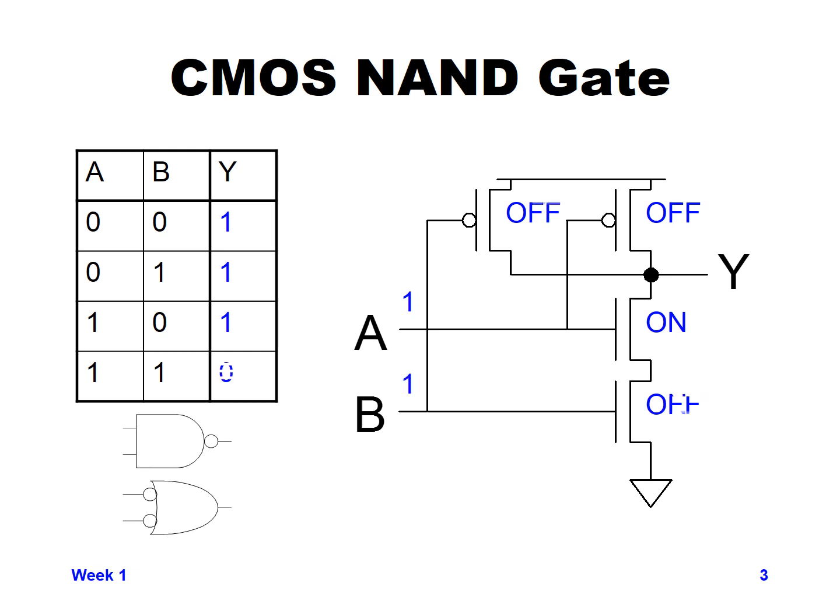and you get a 1 output, a logical 1. Now when both inputs are connected to 1, both PMOS devices are turned off and you have no connection up to VDD. But both NMOS devices are turned on, so you have a connection through the A NMOS device and the B NMOS device down to ground, and it will cause your output Y to be connected to ground, and you get a logical 0 out of the circuit.